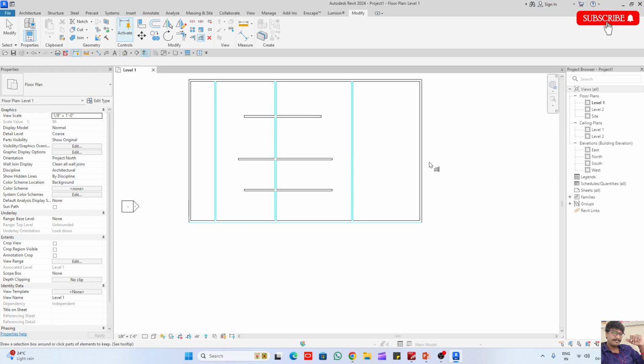Now I want to select this wall. Now click outside, select this one, this one, this one. Click outside. Now I want to select which wall? This wall. Click this one, this one, this one. Now, sir, I want to remove all these three walls up to this wall. So select this one, click left side or right side. If you click left side, right side will trim. Whichever side you want, that side you have to click. So right side you have to click. Understanding now? I want to remove this side. Click this one. Which side do you have to click?